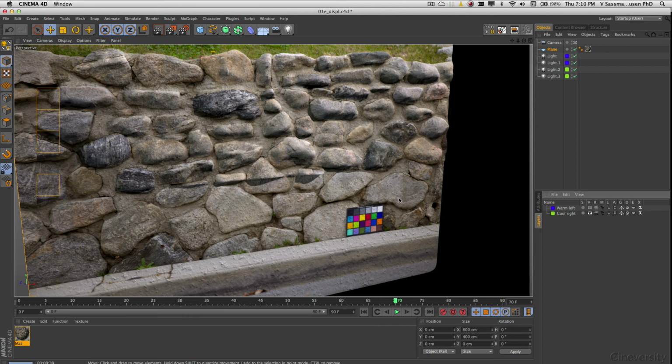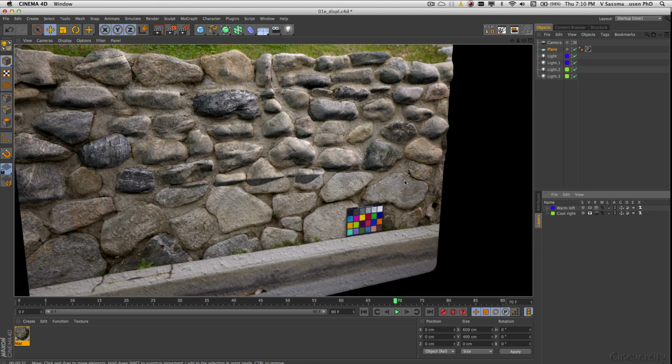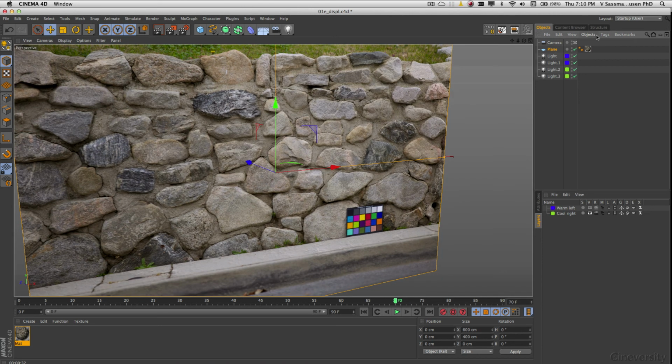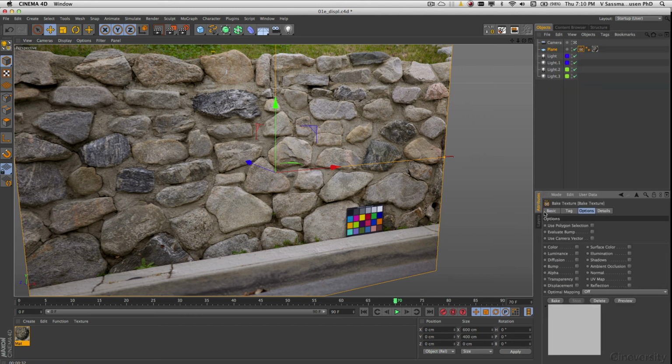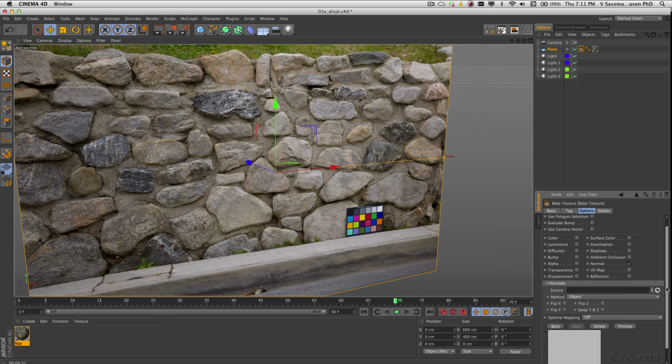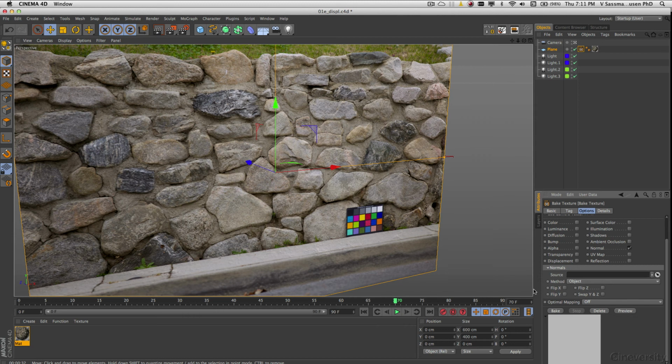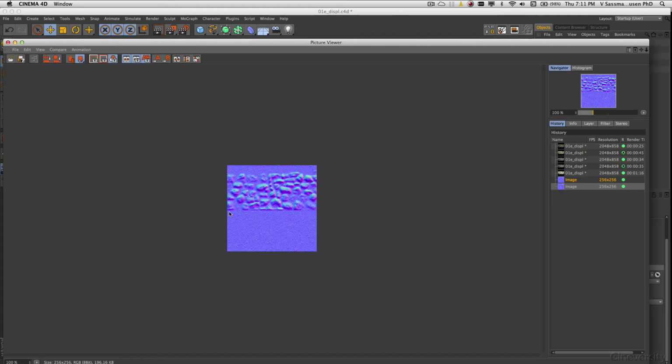So what I want to do here now is, of course, how can I create a normal map from that? That's pretty simple. We go here to the plane, we go to text, we go to Cinema 4D text to back texture, and in the attributes manager we go then to normal maps. We get here a new field, so we can flip X, Y, Z, swap out Y and Z, and so on. I exclude any settings here because this is not a series about texture baking, but when you click here, you get immediately that hard line.